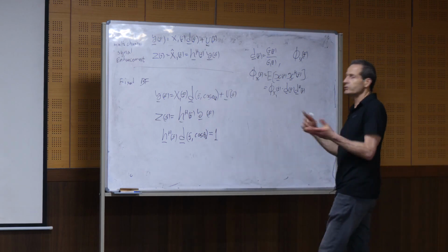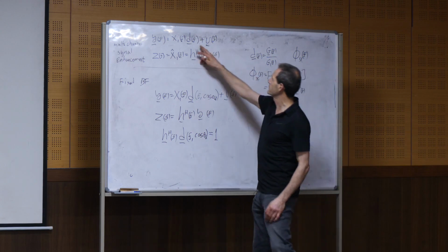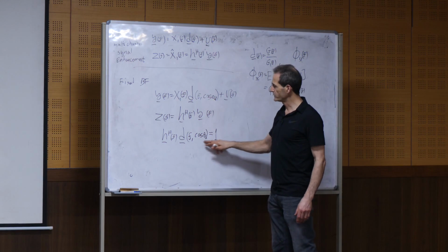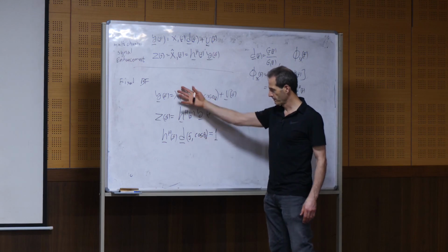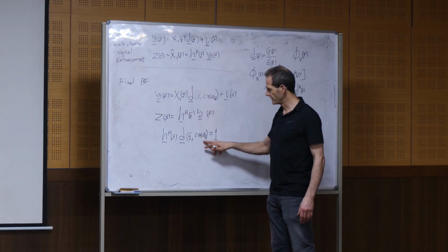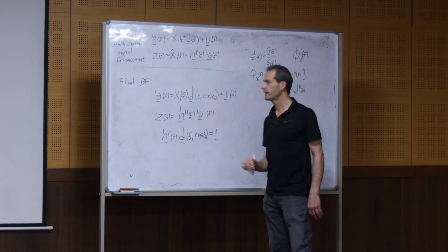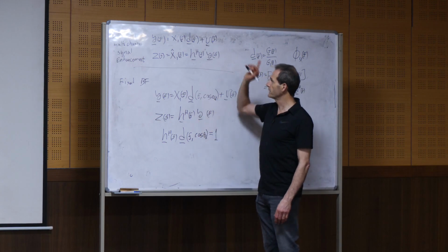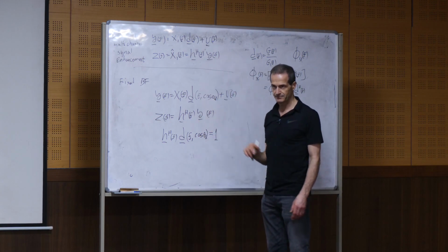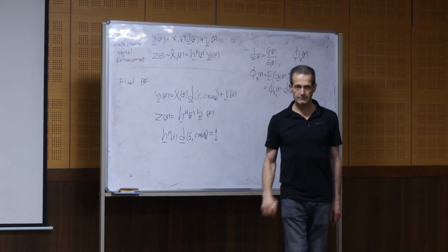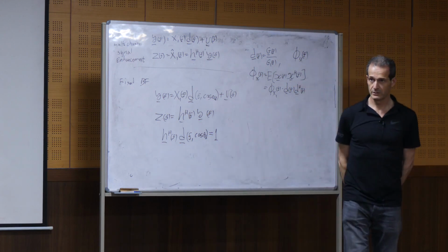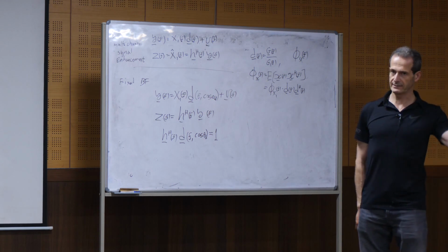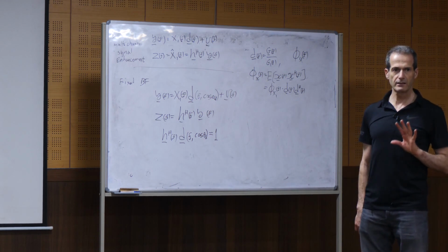But because we don't know the environment, we don't know the relative transfer function, we just know or design the beamformer towards a certain direction, theta d, this is what we apply. So this is the distortionless constraint, which is different than what we used here. In addition, I don't know what the noise environment is because I designed it in advance without knowing the environment.